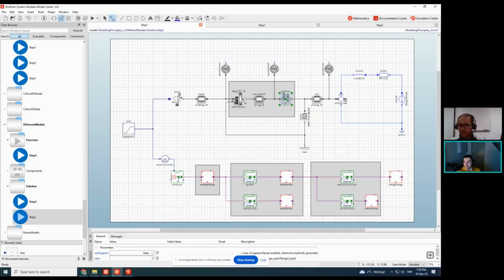Right. And as you rightly said, Vedat, when you think that you don't understand a component, try simple examples, like create a new model, just take the ideal gearbox, take an input, plot it, and see if that is what you expect. Because many times when we use components from different libraries, we have no idea what the library developer thought, or what mechanisms he has in his component.